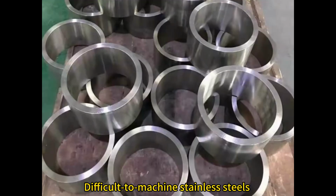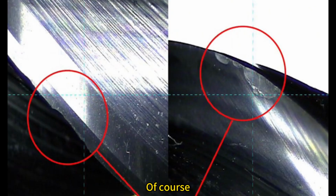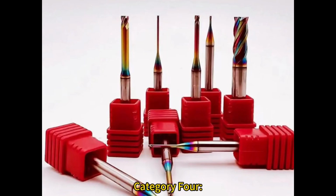Category 3. Difficult-to-machine stainless steels and high-temperature alloys, such as 316, 317, duplex stainless steel, Hastelloy, titanium alloys, and nickel-based superalloys, can share the same tool. Of course, nickel-based superalloys are particularly challenging to machine and wear tools faster, so custom tools are highly recommended. Important note: tools for this category can also process materials in Category 2, such as 303 and 304, and can be shared.